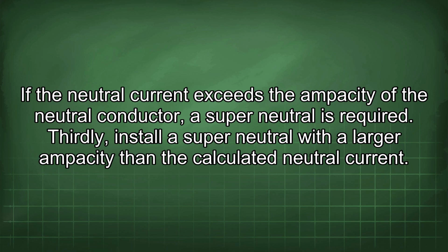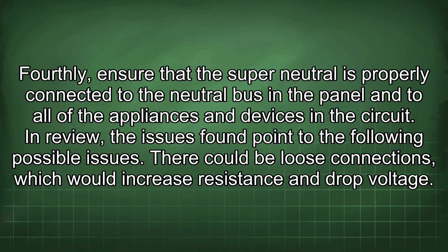Thirdly, install a superneutral with a larger ampacity than the calculated neutral current. Fourthly, ensure that the superneutral is properly connected to the neutral bus in the panel and to all of the appliances and devices in the circuit.